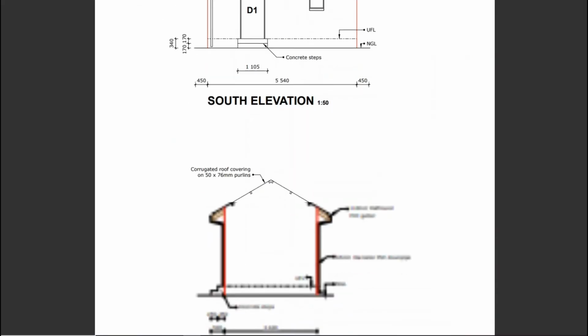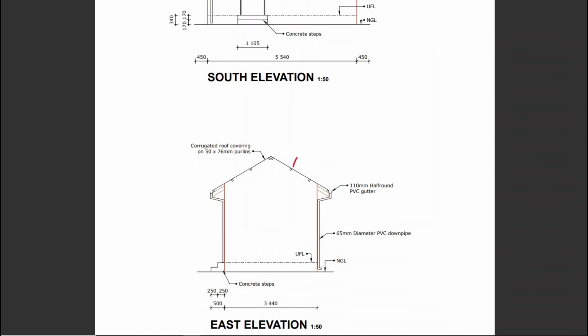And we'll go over to this example. This is 345. But that does not necessarily mean that on slope is 345. In fact, it cannot be. This on slope is shorter than 345. And how much is it shorter by? Well, it's the reverse. You're going to have to divide 345 by 1 over cos 28.